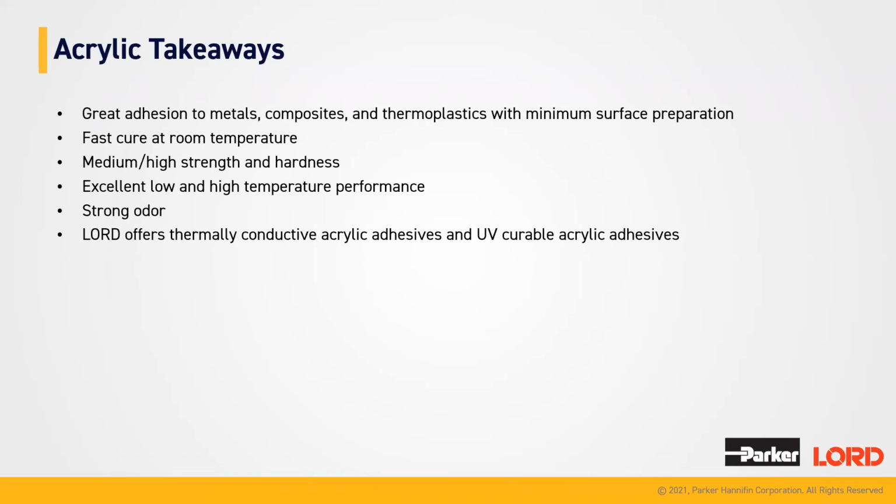So super valuable there. Now, one of the main limitations that I mentioned earlier is it does have a strong odor. So that methacrylate smell is quite strong. And Lord also does offer a thermally conductive acrylic adhesive as well as a UV curable adhesive in TC 2002 as well as AC902LC.